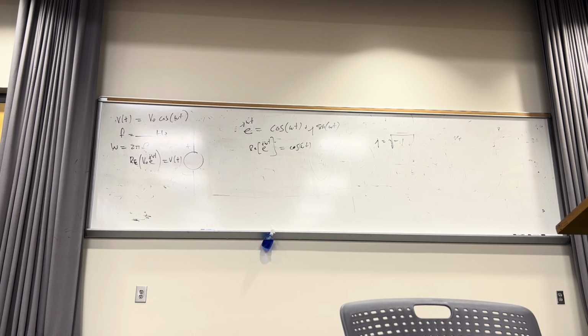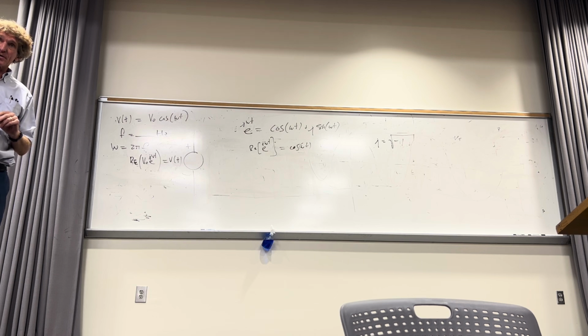Then you can solve for these, what they're called phasor currents and voltages, and I'm going to show you how. And you can take those and very easily solve differential equations. And instead of having all these integral differential equations, you have algebraic equations that you can solve.